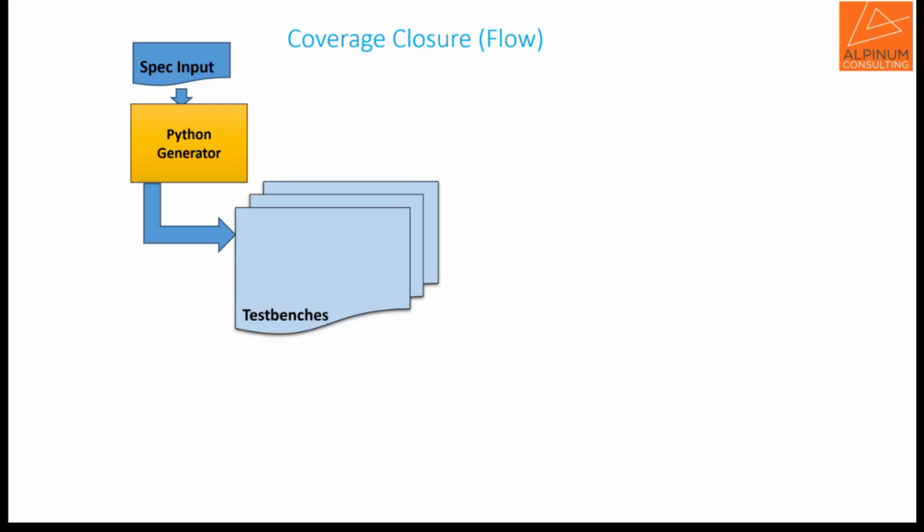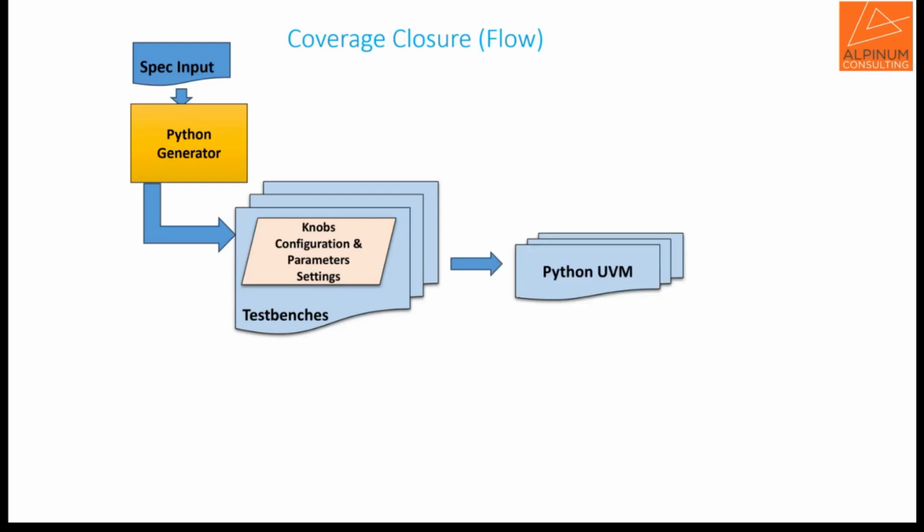Then we have the simulations going on as the test bench runs, and all the regression results are generated and optimized by how we are constraining them. But the most important thing here is to show how the coverage is optimized from the coverage scores that we measure after each set of regression run iterations, and it controls how we are going to feed the next set of regression data for the next set of iterations.